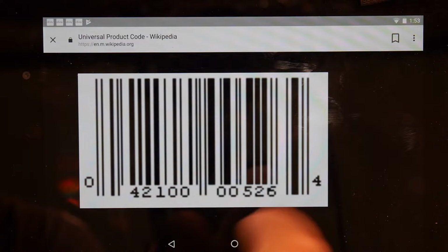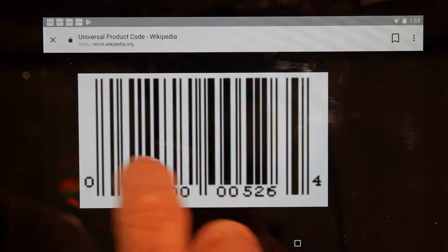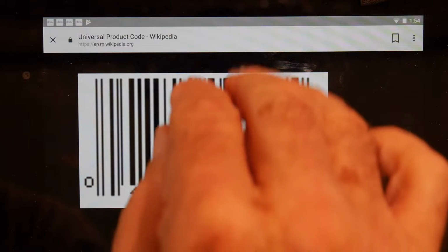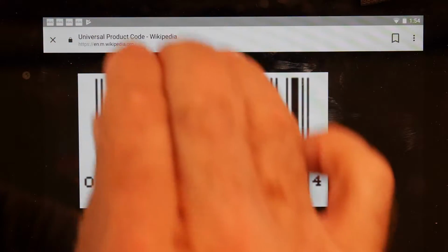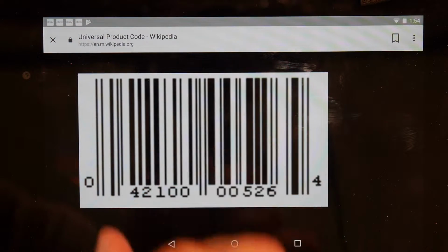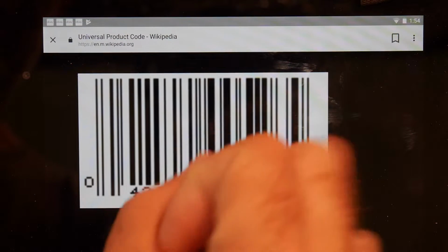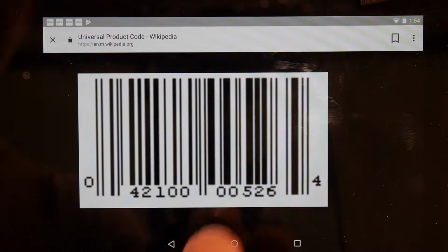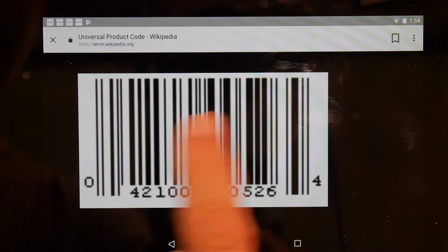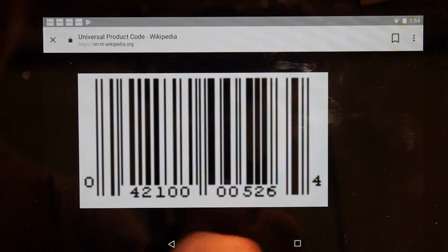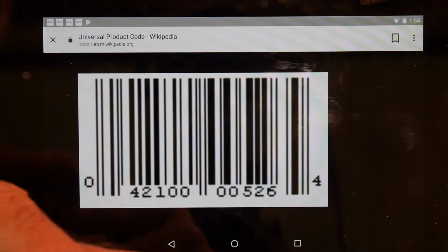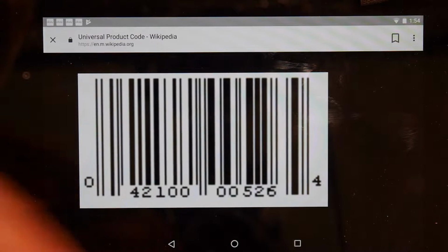So you imagine if you're building a circuit to decode this, you're going to be scanning an analog signal. The analog signal can vary up and down. It doesn't reach full white, it doesn't reach full black. It kind of varies depending on your spot size of light. You may not be able to resolve these things completely, so there may be a small modulation, a big modulation. These things are printed in different colors and different densities, and so you need something that can track things along the way. The other thing is if you have a flying spot, it can actually have an acceleration.